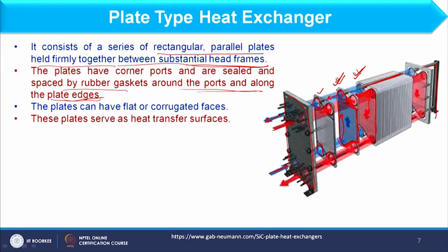Okay. And how do we ensure that only cold fluid will enter and only hot fluid will enter? That is because of the gasket. Okay, I have already explained how the gasket is placed. So, it will not allow another fluid to enter into one plate, or we can say the mixing of fluids on a plate, which is not possible over here. Okay. So, separation of fluid will occur through this gasket.